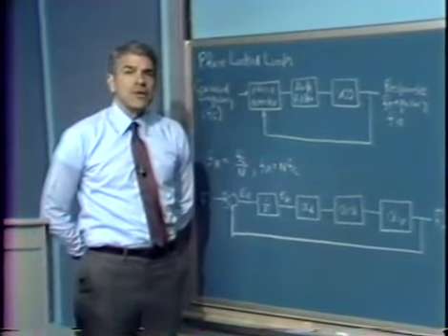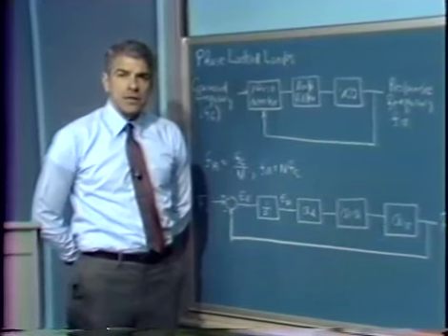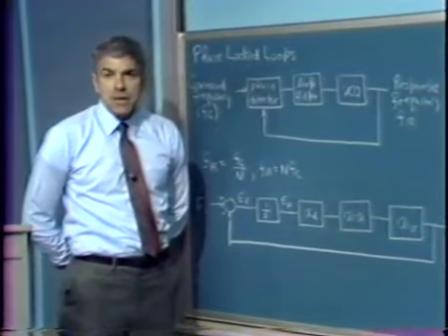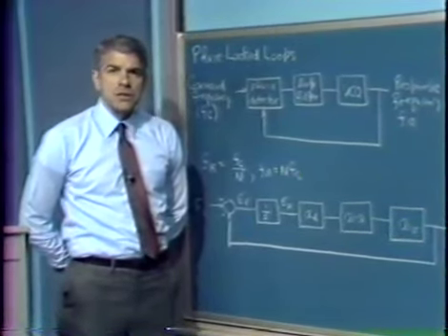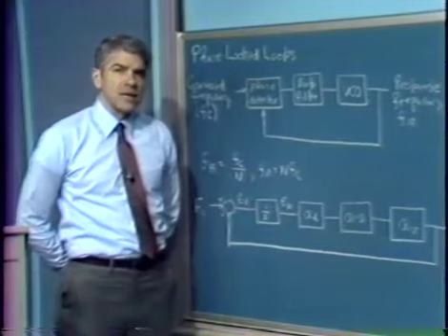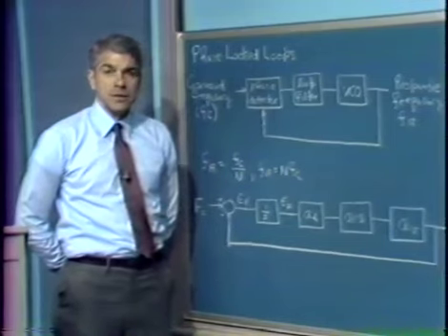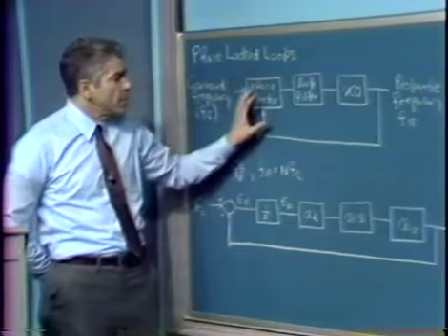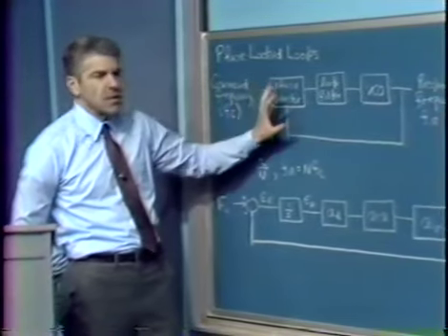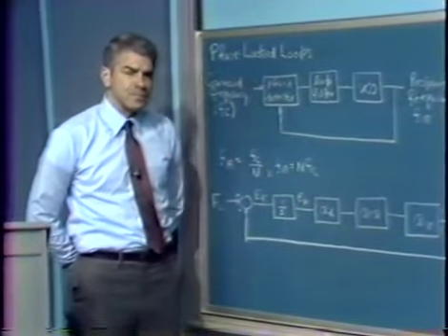Typically in those sorts of applications, because the input signal may be quite noisy, we get filtering out of the phase-locked loop by making it a narrow-band filter, by effectively greatly reducing the crossover frequency of the feedback system that mechanizes the phase-locked loop. That crossover frequency becomes approximately the filter bandwidth, and we're able to then recover a fairly noisy carrier signal and use that in a further demodulating process in a communication system.